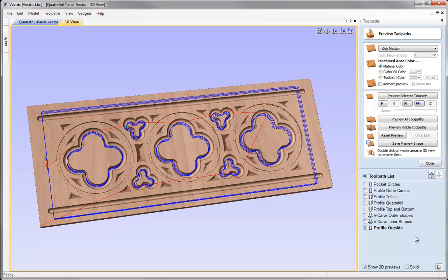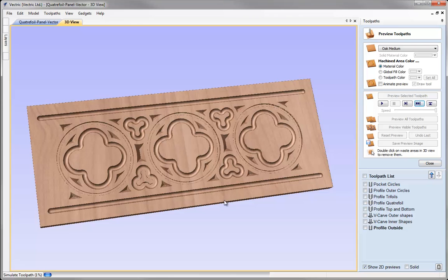So now we're happy with that, we can go ahead and preview the toolpath. But instead of previewing it all in one go, we could step through the toolpath to ensure that the inside pieces are getting cut out first and not the actual cutout for our part. We can do this by using this button here, run to retract. It does it step by step, so every pass depth will count as a retract. I'm just going to click this once, and you'll start to see that this shape has started to be cut out. So I'll just do that again.